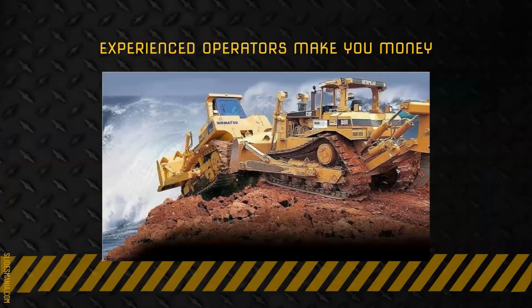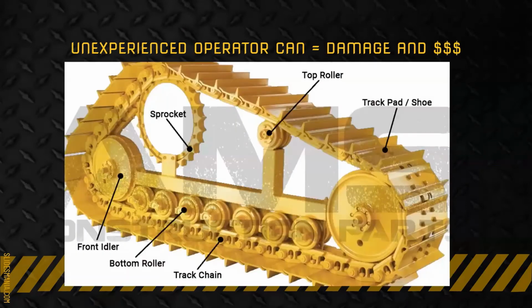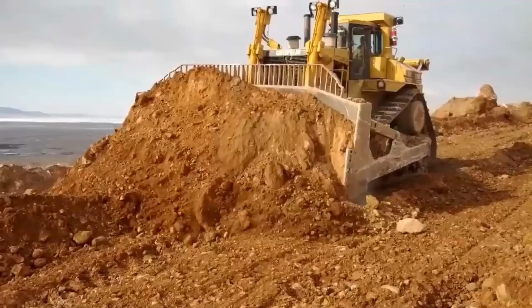It may appear easy to operate a dozer in the video, but it's much harder than it looks. An experienced operator is essential to production during a job. A few problems that can occur from an inexperienced operator not using the dozer efficiently are that there will not be material readily available for the scrapers to pick up and move. Also, an inexperienced operator could easily overheat the idlers and rollers and cause some serious damage to the dozer and its tracks. The type of material is very important to take into consideration when bidding a job.